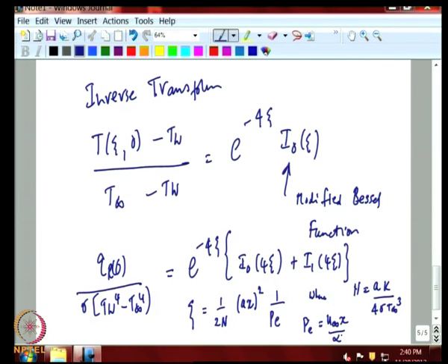So, finally, the functional dependence of temperature and flux depends upon the conduction radiation parameter here in terms of absorption coefficient, in terms of the conductivity of the gas, Stefan-Boltzmann constant, and temperature of the gas at infinity, and the Peclet number.